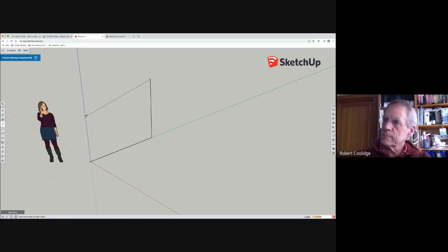If I tap the right arrow, I don't need that. The left arrow is green. And between the two of them, I've just made something that aligns with this point below and is on that axis. And when you complete the last thing, it created a rectangle and closed it in. So SketchUp is a surface modeler. In the world of SketchUp, everything consists of basically 2 elements. They're edges and faces.